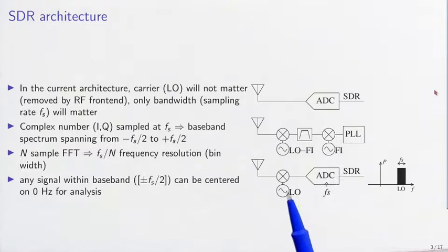And the current software-defined radio architecture will not feed a radio frequency signal directly to an analog to digital converter, because of its limited resolution at high radio frequency and the loss of dynamic range if a strong interference lies between 0 Hz and the sampling frequency of the analog to digital converter. So an initial frequency transposition is performed by a local oscillator. This is a hardware level. Data is sampled at a sampling frequency fs, and all further processing is completed at the software level.